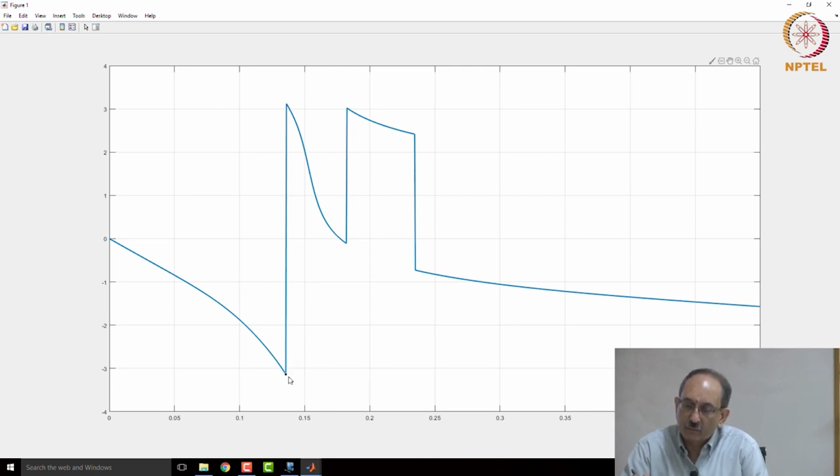Therefore, at this point you add 2 pi and you reach this point. Then the phase response keeps on decreasing, and now you hit the first 0. Therefore, this jump is now pi when you cross the first 0 on the unit circle.